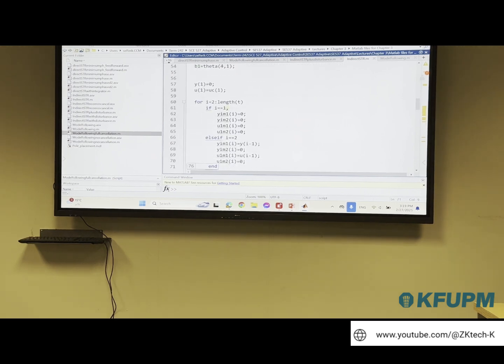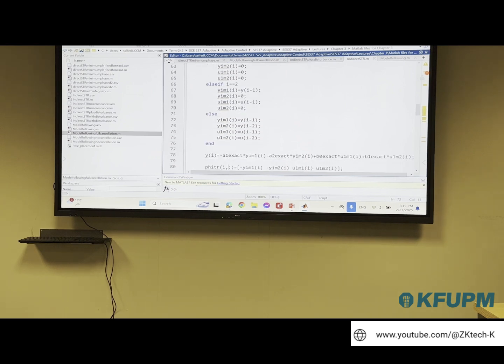Of course, here in the loop estimation, when you look at your difference model, since you have q squared, at that time you need to write it as q to the power -2, etc., and make the time shift in your domain. So the time shift will give you y of i minus 1, this is here. Then you have y of i minus 2, plus u of i minus 1 and u of i minus 2. This is just my way of coding.